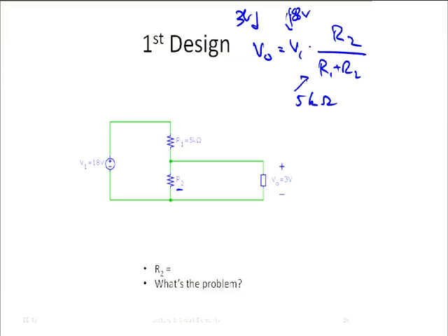So we can do that, but there is also a more clever way. The current here is flowing through both resistors. What's the drop that we want across resistor R1? Well, here we want to have 3 volts. Therefore, across R1, we need to have 15 volts, right? So the voltage drops across these resistors are, of course, proportional.